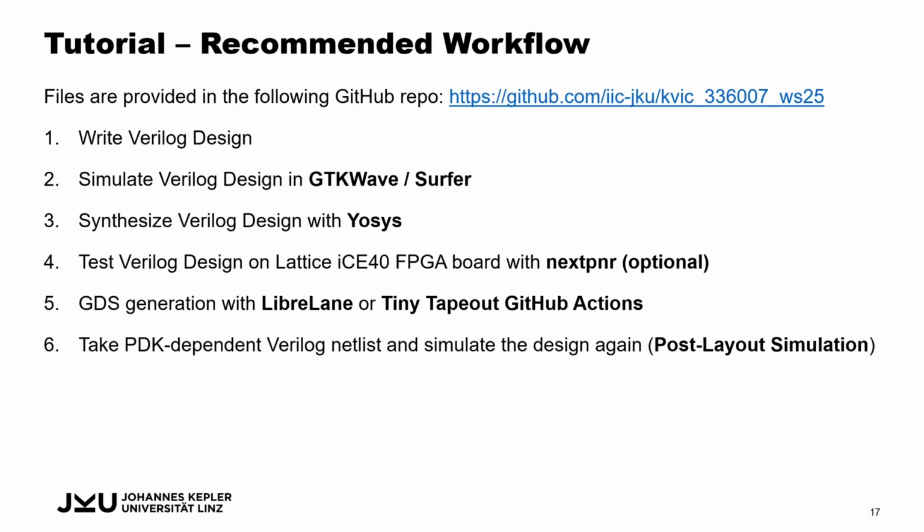So the first step is, of course, write your Verilog design and simultaneously always simulate this design in GTKWave or Surfer. Then afterwards, synthesize the design with Yosys and check out the hardware statistics. If these, for example AND gates and registers, are roughly the number you have imagined for your design, then we can say, okay, the design is good and there is nothing unexpected.